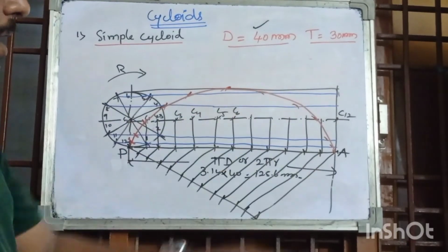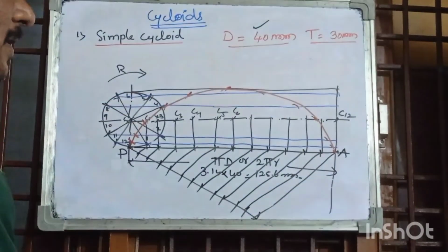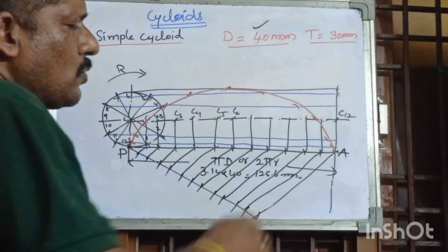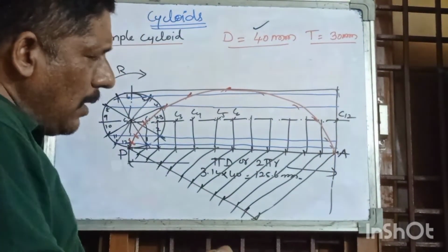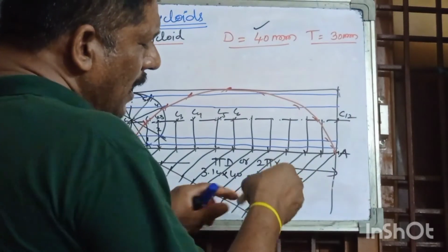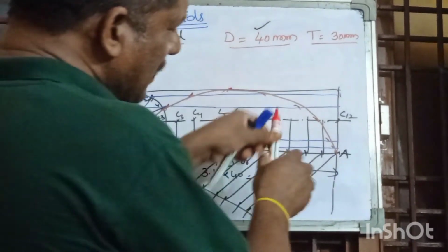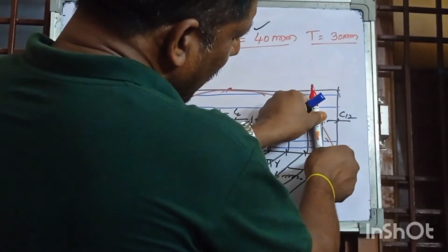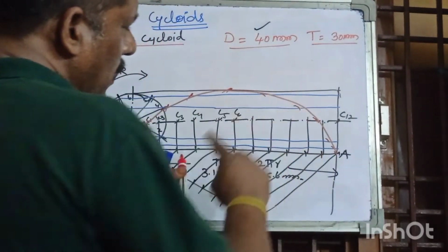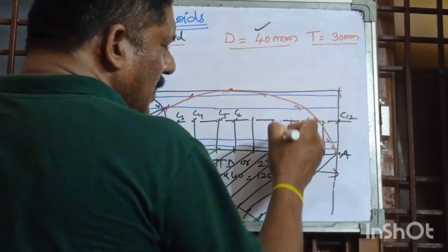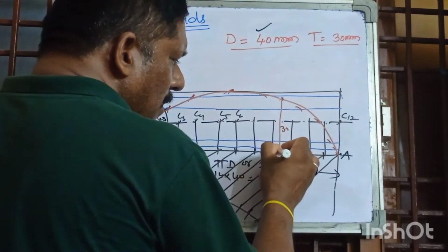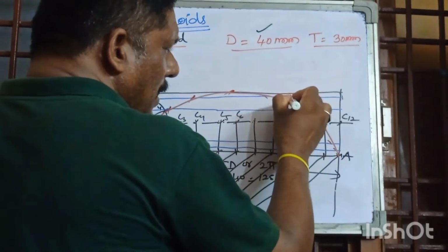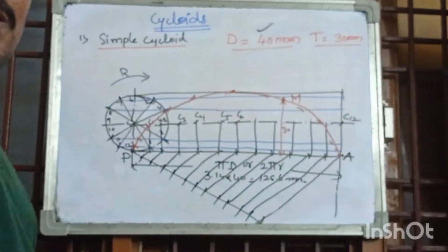So after getting this curve, we have to go for the tangent. It is given 30 mm. So from this point, from this supporting line, take a scale like that, keep the scale like that at 0. See where you are getting 30. So from this point, straight where you are getting 30, mark the point. Suppose this is 30 mm. Mark that point, name it M.